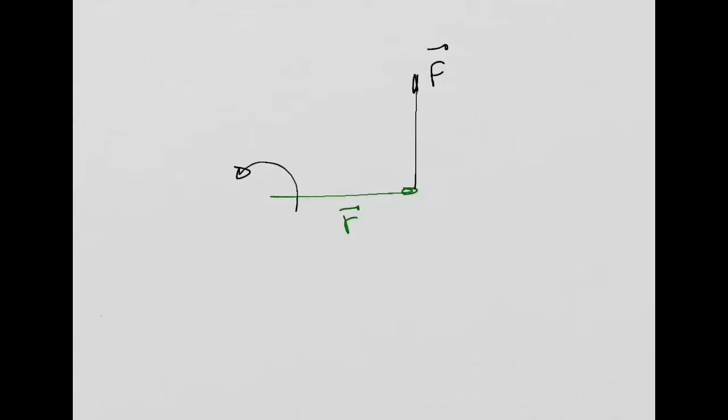if you use your right hand and if you align this with the position vector, so let me try to do it here graphically. So you have the position vector and you have the force vector here, right? So when you calculate the moment, if you align your fingers of your right hand with your position vector like this, and then if you try to rotate your fingers from R towards F vector, you rotate like this, right?